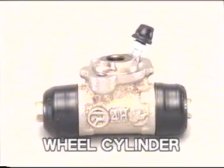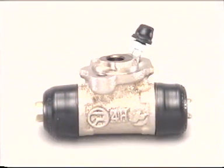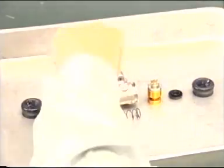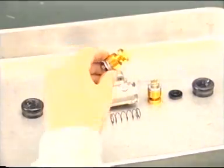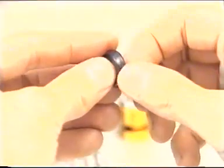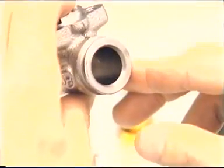Here are the wheel cylinder overhauling procedures. Disassembling the rear drum brake is not so complicated. Inspect the parts. Check for any damage on the piston cup or inside of the cylinder.